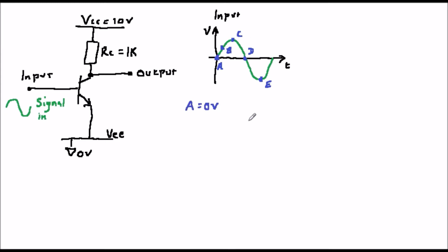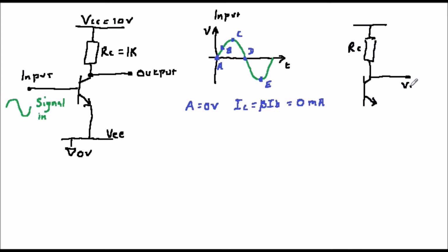a transistor. IC is equal to beta times IB, as we've learned before, and since IB equals 0, this means that IC equals 0. So there is no voltage across the collector resistor, because this voltage is equal to IC times the collector resistance, and IC is equal to 0. So we have a situation which is shown on the diagram on the screen.